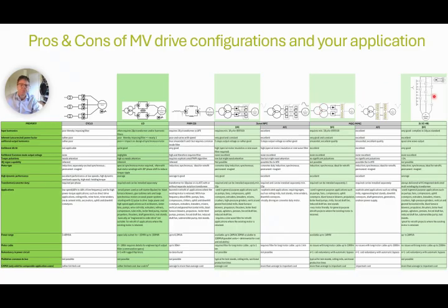The 2-level series Cascaded H-bridge adds up the output of multiple low voltage power cells to obtain medium voltage levels. Each power cell is in fact a simplified version of a standard 2-level PWM low voltage drive with a direct front end. Therefore, this drive delivers the same excellent power factor as the ones we mentioned before with direct front end.